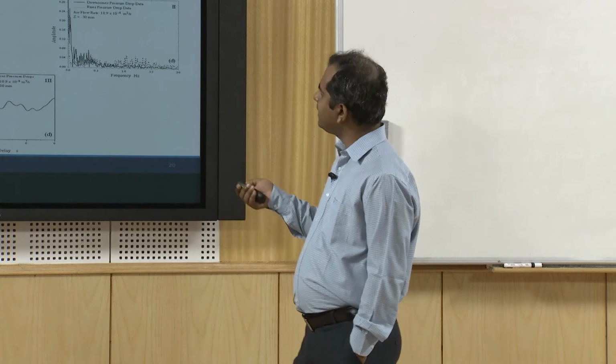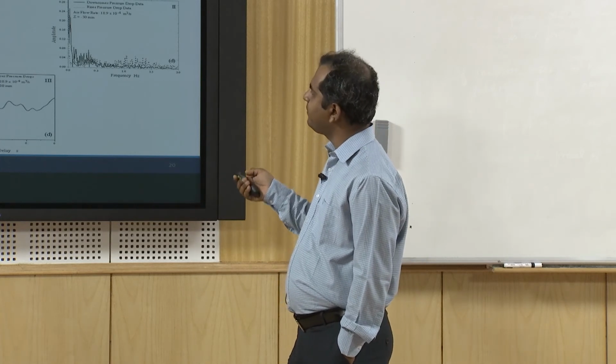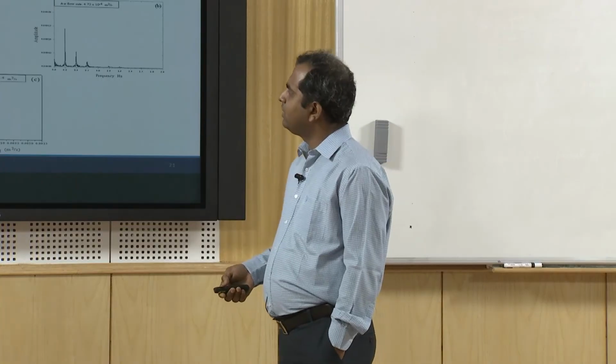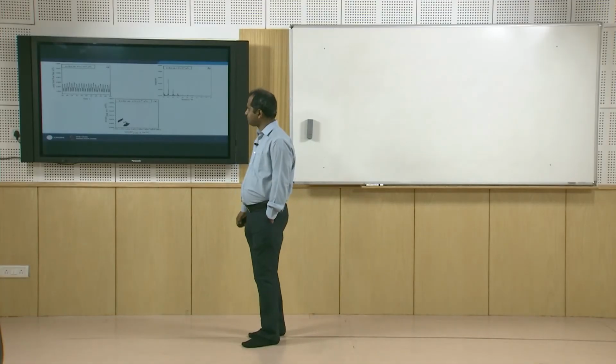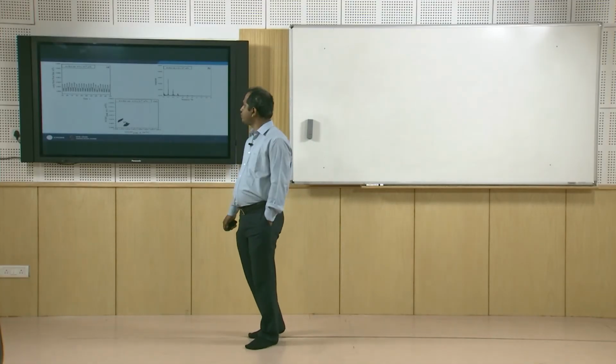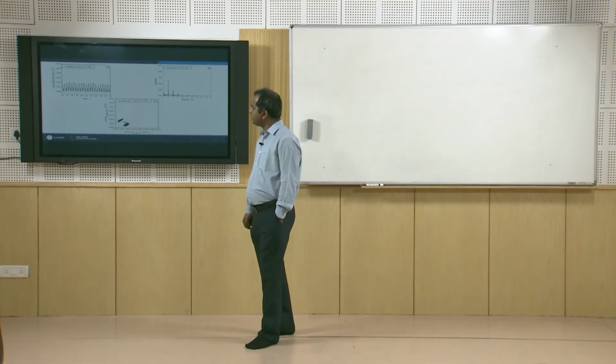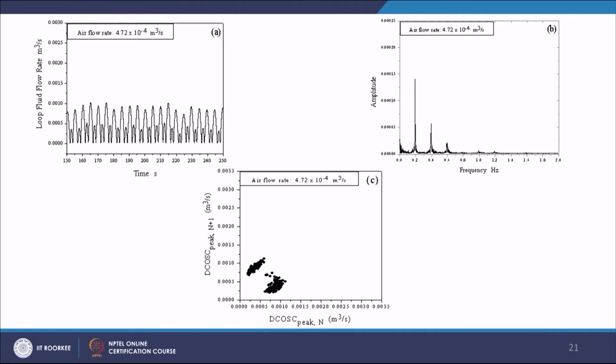So, here you see the PSDF also looks very chaotic, and if you try to correlate, that means the cross correlation, then you will find it is not showing the earlier nature whatever you have observed in the previous one. Okay. If you increase the velocity further, you will get a far more erratic nature. Another important technique I will be showing you apart from this PSDF is called a scatter plot.